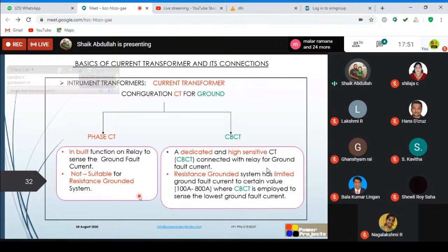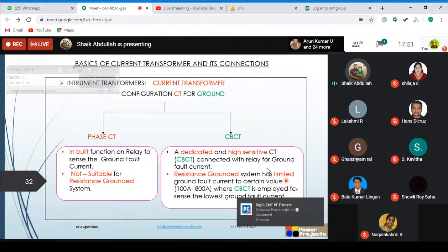As I mentioned before, we can use the CT as the important device for your relay coordination. Since the current transformer is your important sensing device for your relays in medium voltage, for phase overcurrent, for earth, for any ground or neutral, you have to use CTs as input.